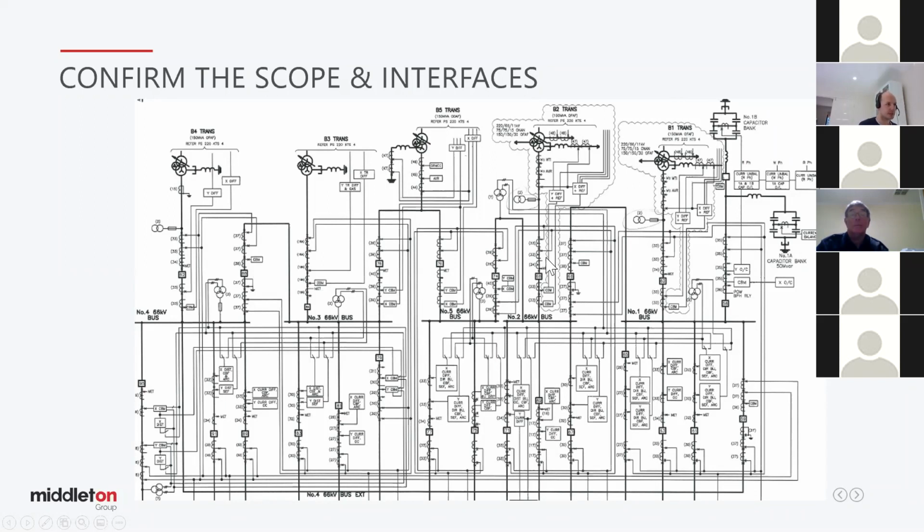Moving down from the transformer protection, you can see here we've got duplicate circuit breaker management schemes, and they're really used for monitoring and controlling that 66 kV breaker, but also performing CB fail, circuit breaker failure. So that's part of any requirements. That's number one. That's the first transformer.